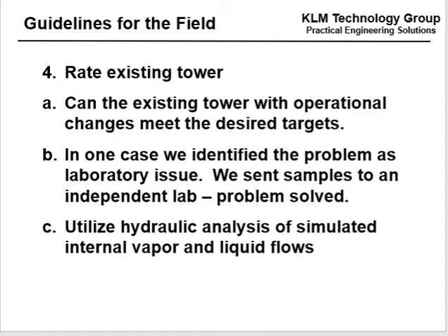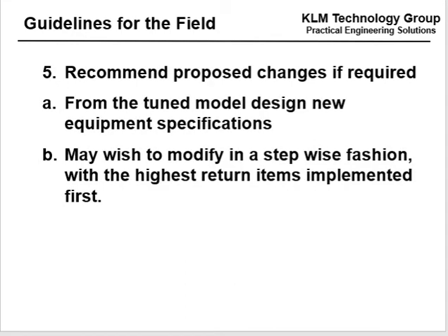Rate the column. Then utilize the hydraulic analysis of simulated internal vapor and liquid flows. If you're really going to be a good simulation person, you also need to have hydraulic knowledge and a small amount of knowledge of how the trays are designed. It will help you in your simulation. Recommend proposed changes if required from the tune model.